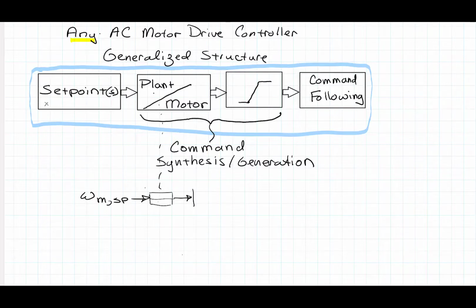But then here you need to ramp the set point. So you basically know that you're going to start the motor, say, at 0 speed, and it needs to go up to the set point value, because you can't just step from one point to another. And actually what happens here is really to calculate the ramp rate. So that's at least one thing that has to happen in this block. How fast can you ramp the speed from one point to another has a lot to do with both the plant that you're controlling and the motor itself. So as a minimum, this block right here would be finding the ramp rate and putting some meaning on that.